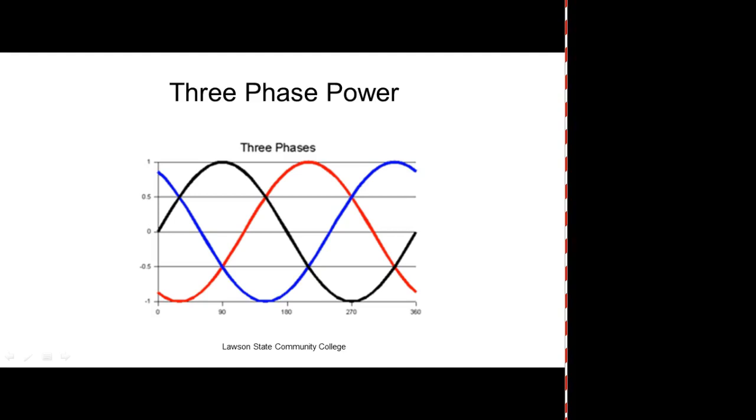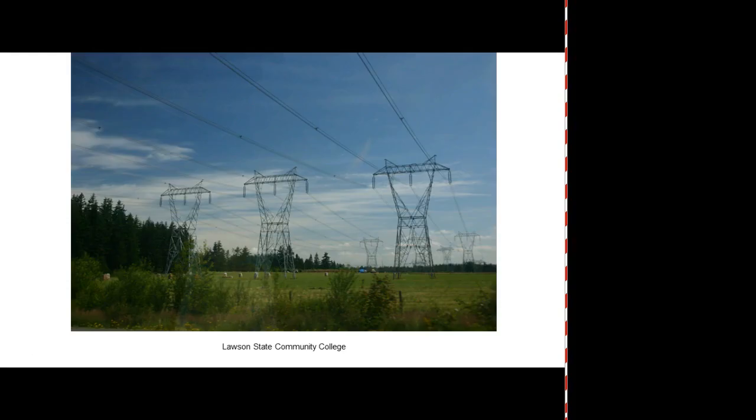Now what advantage does 3-phase have over single phase? Well, what happens is the power is distributed across 3 wires instead of across 1 wire. So that means if you measure the voltage and current in one conductor and you multiplied it, you're getting more power than you're getting out of that one conductor. So the power, instead of being on 2 conductors, is actually spread across 3 conductors. So we can send more power with less current. And we sacrifice 1 conductor and it's a lot more efficient.